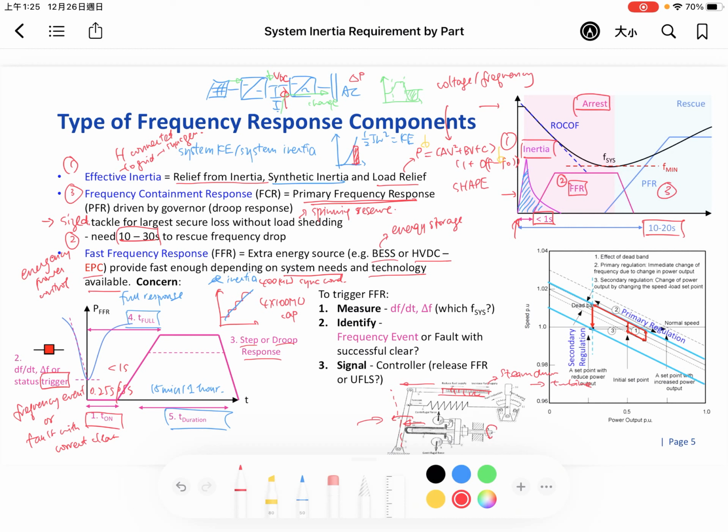But of course we want to have some control. That's why we have the spring to damp the opening, and also the screw to provide control on the minimum or maximum opening. The minimum is to close the whole valve, and full response is to open the full valve. Then it is the frequency response, and the droop is like that. It is often a 4% droop.